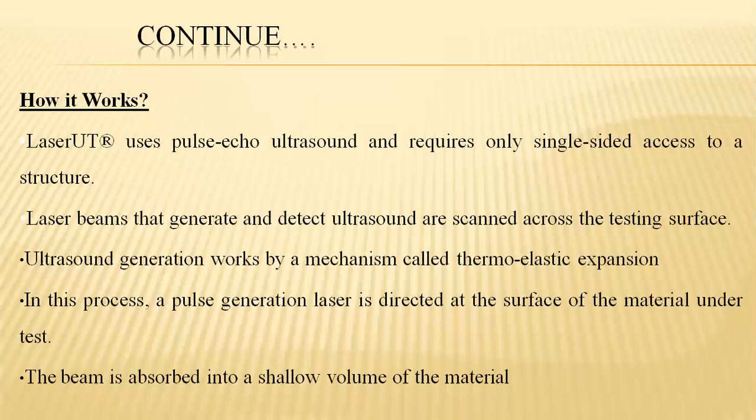And this ultrasound generation works with a mechanism called thermoelastic expansion. Particularly in this process, a pulsed laser is directed at the surface of the material under test.